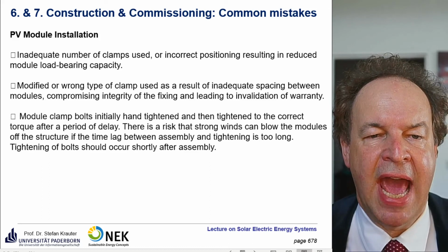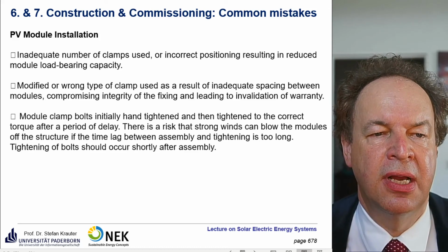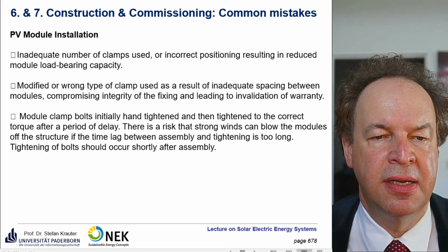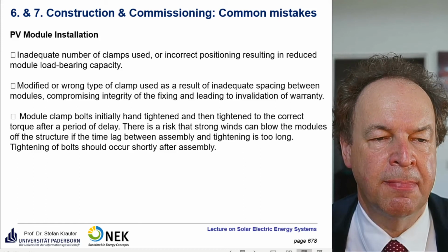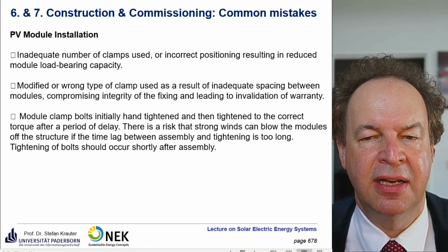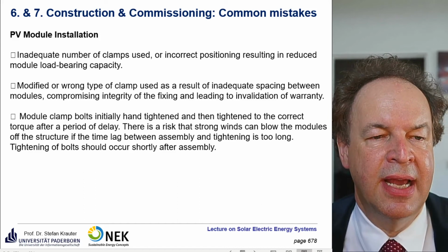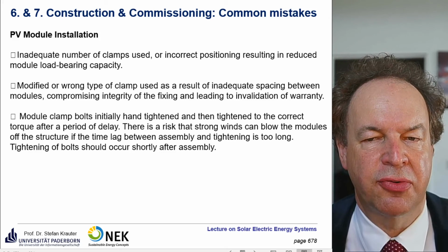Module clamp bolts initially hand tightened and then tightened to the correct torque after a period of delay. There's a risk that strong winds can blow the modules off the structure if the time lag between assembly and tightening is too long, and the tightening of bolts should occur shortly after assembly.